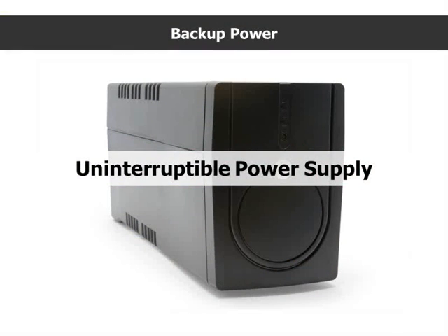The first is a UPS or uninterruptible power supply. This actually takes AC input from wall power or data center or something else. It also filters power. But if the power ever goes out, it will supply power for some predetermined period of time to devices. Many times, it can be a fairly short window of opportunity, which just simply allows for proper shutdown of equipment. Some UPS arrays can actually go for a longer period of time.